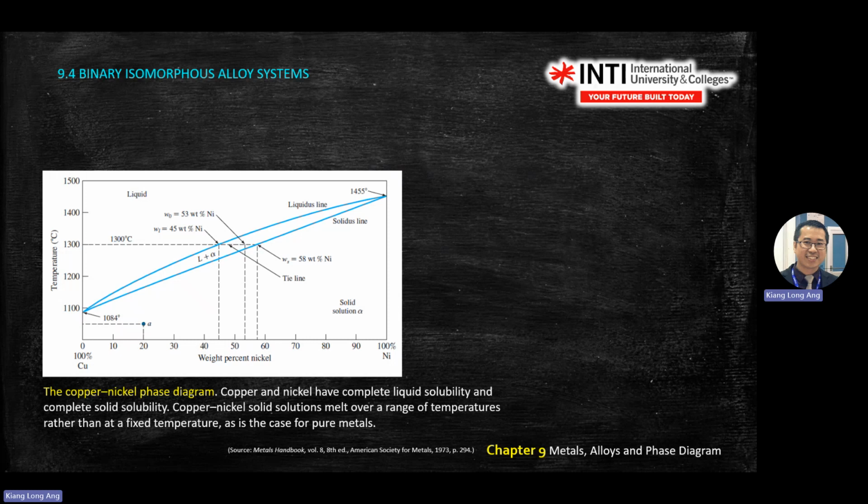So we have two types, one liquid and one solid, in this region between the boundaries. Then on the line here, what the blue line means is a two-phase equilibrium state. It means two phases can coexist, because you're walking on the line. Like you're seeing left or right, you're seeing liquid or liquid plus alpha.